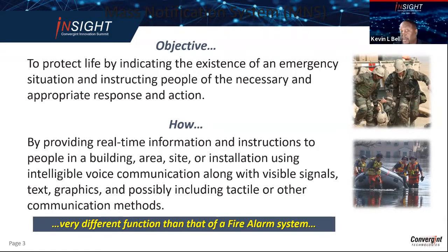One of the easiest ways to do that is to pull a fire alarm pull station or set off a sprinkler head. Everyone will evacuate into their muster stations, and that ex-employee typically will know where the muster stations are. He'll wait out there with his gun and pick them off. So this is why NFPA code allows mass notification to supersede fire alarm.